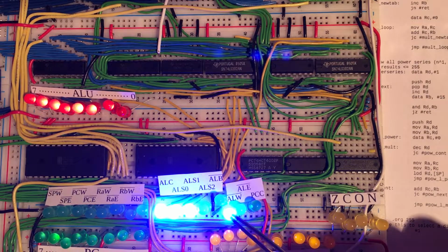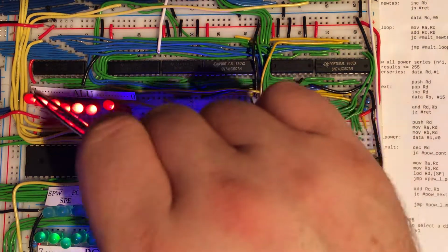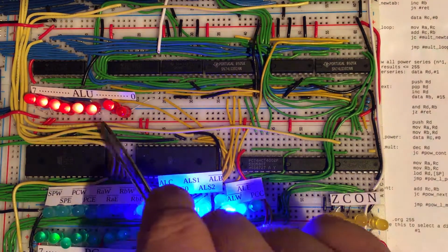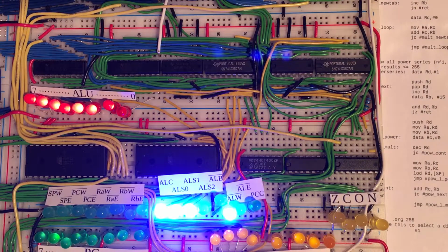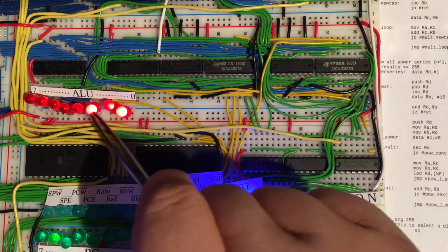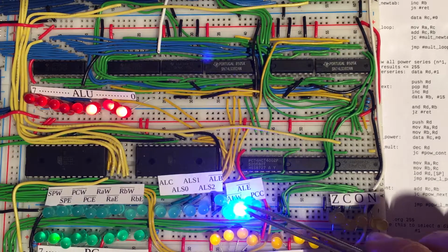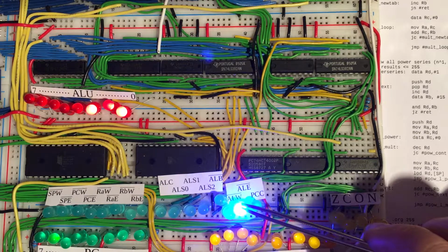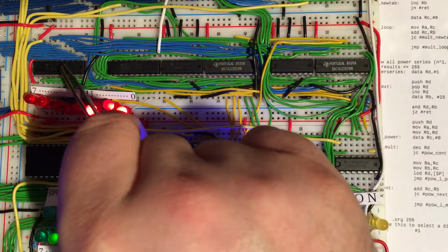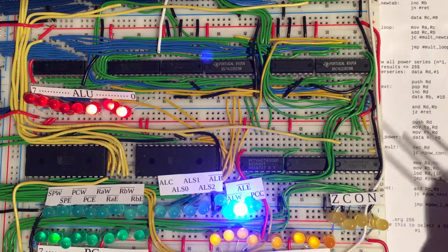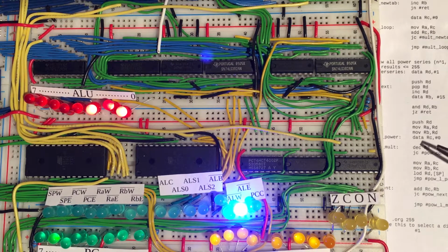And once again, the result of that calculation is going to be latched into this special register that we have for the ALU. And so on the next rising clock edge, we should see a value of 7, because the bus is asserting a 6 right now, written into that register. And so there's the 7, which is 3 1s in binary. And so on the last part of the instruction, that value is now being output from that register through this buffer onto the bus. And then the D register is going to write that inside of itself, because it's going to enable its write signal. And so that will be the conclusion of this increase D register instruction.